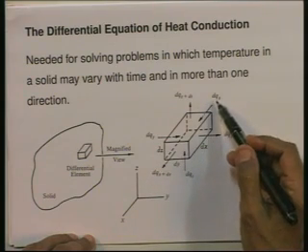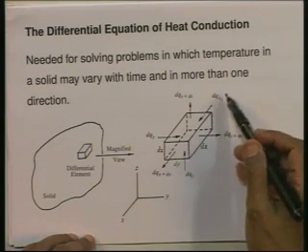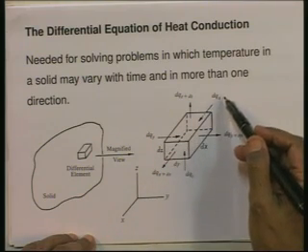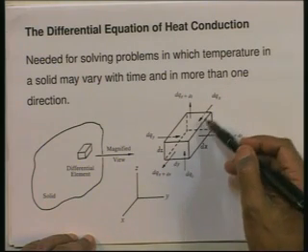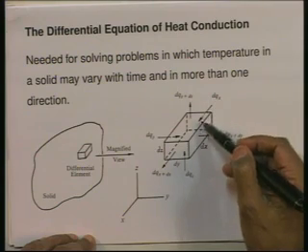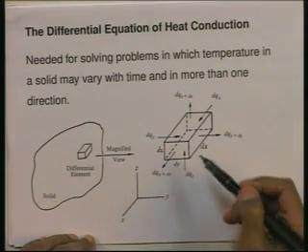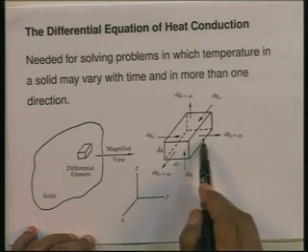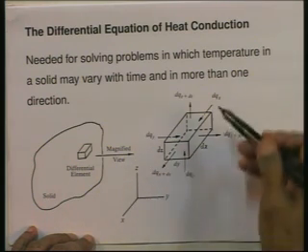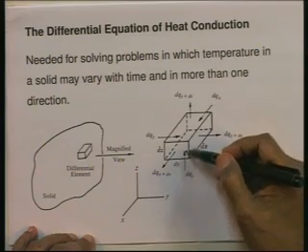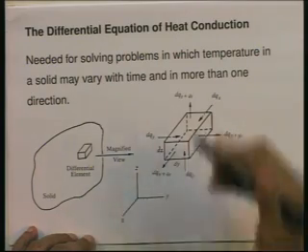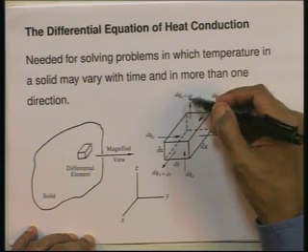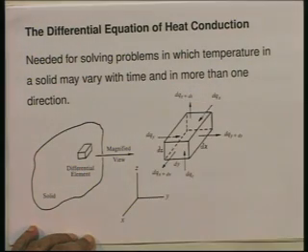So, for the two faces which have their normal in the x direction, the heat flowing in the positive direction is dqx and dqx plus dx. Similarly, for the y direction, we will have dqy, dqy plus dy, and for the z direction, we will have dqz, that is the bottom face of this element, and going out from the top face dqz plus dz.